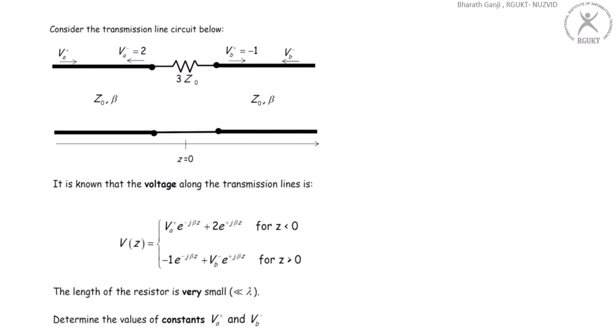So these questions are regarding the boundary conditions. Here some transmission lines are given, and in the middle they are connected with some kind of circuit element whose dimensions are very much smaller than the wavelength, so you don't have to apply transmission line analysis for these links also. The connecting wires which I have highlighted here don't need to be considered as transmission lines. They are simple connecting wires where you can still use your network theory, or you can neglect the transit time effect in this section.